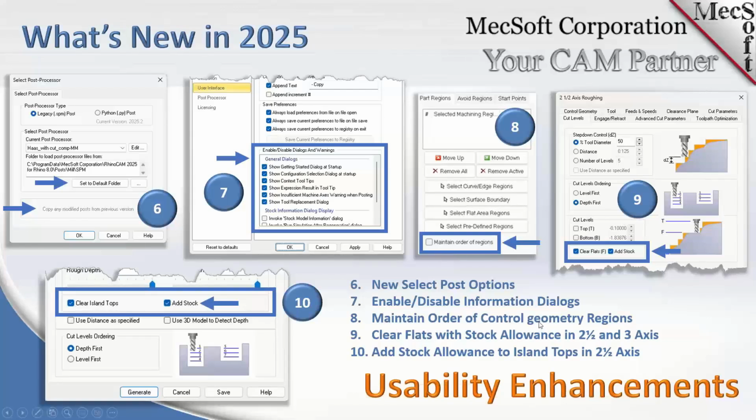Number 8 is another very helpful enhancement. Maintain order of control geometry region. In each of the toolpath methods, you'll see that you have your area where you can select your control geometry, be it part regions, void regions, et cetera. Previously, you may have thought that they were processed in the order that you see them here, but there's a lot of processing going on in the background, which causes that maybe not to be the case.